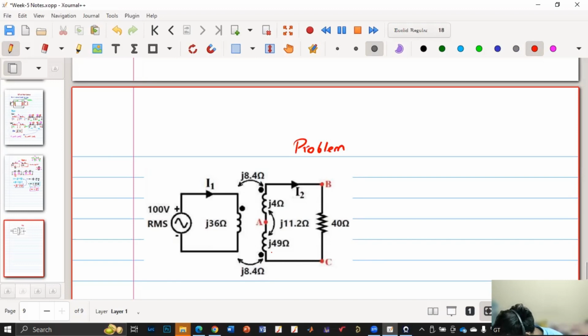If you draw the polarity correctly, then it is easy. Now we need to check which case L1, L2 comes under, and which case L2, L3 comes under. They have given the current direction. In L1, current is entering the dot, in L2 current is leaving the dot. So which case is it, case 1 or case 2?